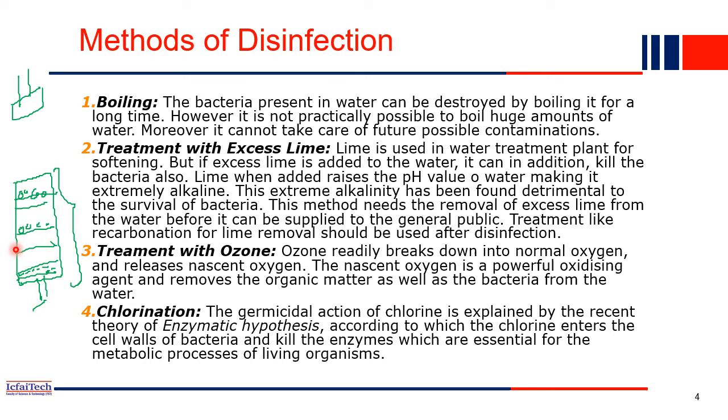The alternative for disinfection, the second option, is the treatment with excess lime. Lime is used in the water treatment plant for softening purposes. We use this lime for softening, right? But if excess lime is added into the water, it can in addition also kill the bacteria, right?